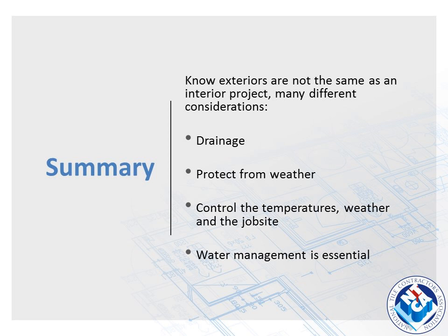In summary, exterior installations are not like an interior project. There's a large variety of things to consider. Again, drainage. Where's your water going when it's draining? Is it going down the face of the building, down the fascia, discoloring it? Make sure you have a place to drain that water. Do you have a deck, for that matter, that runs into scuppers that are 1/2 inch or an inch too high? It's not going to drain.